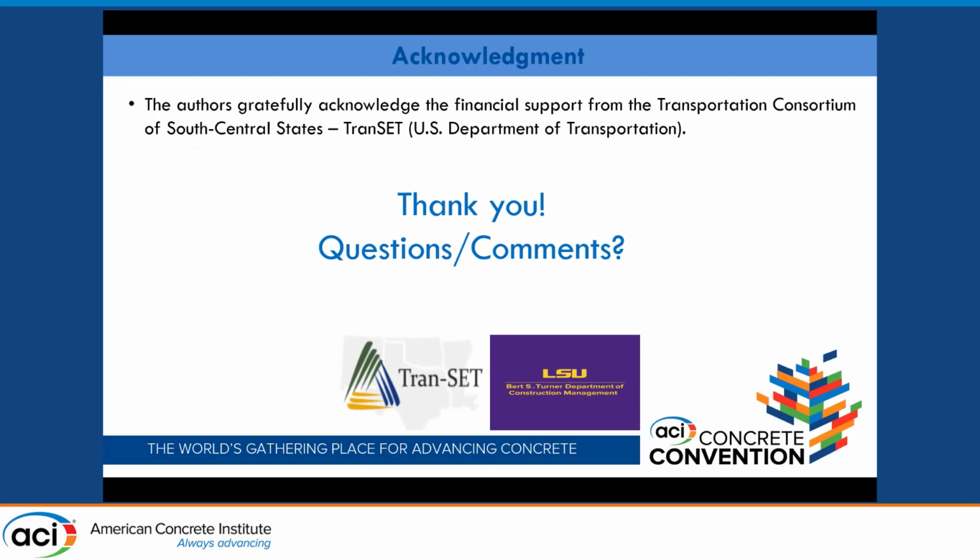Thank you. Just curious, when you proportion your sand and cement, is it by volume or by weight? By volume. Volume? Yeah. Thank you. Did you use any viscosity modifying admixtures? For these samples, no. But in the preliminary stages, we played with various VMAs just to see if we could improve the buildability. But for the steel fibers, for the results I've presented here, no VMA was used.